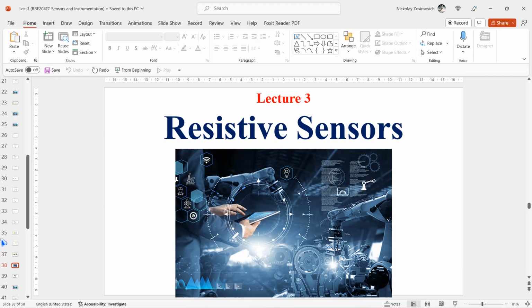Another part of our lecture is the resistive sensor. The sensors presented in today's lecture are all based on the resistive effect. Namely, they behave as an electrical resistor whose resistance is affected by a particular physical quantity. Quantities that can be measured using a resistive effect are temperature, by thermistor and metal thermometer; light, by light-dependent resistor; deformation, by strain gauge; and magnetic field strength, by magnetoresistor.